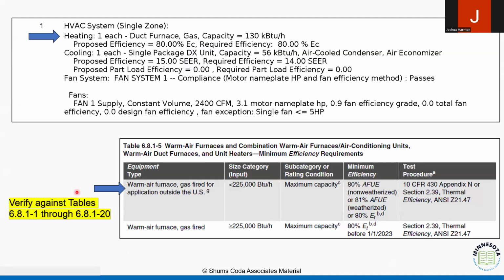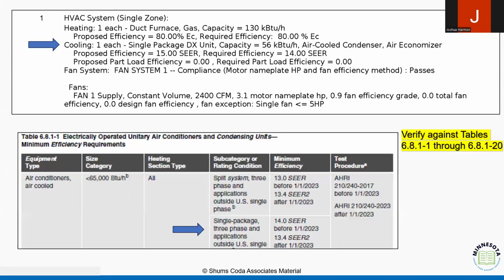And so I'll still have to evaluate each one of those pieces of equipment, looking at their heating requirements, to verify that they have the appropriate efficiency listed, as well as the cooling requirements, right? And what I'm expecting to see in each one of those systems.